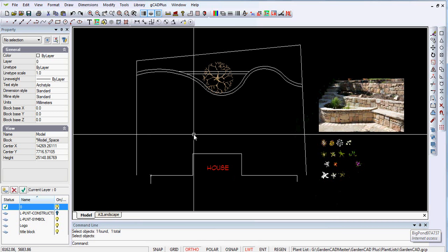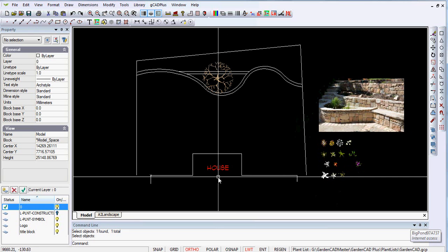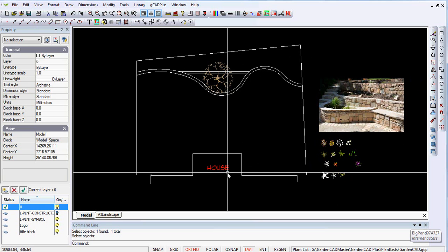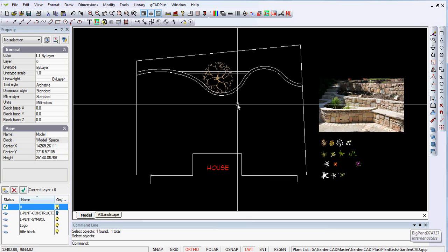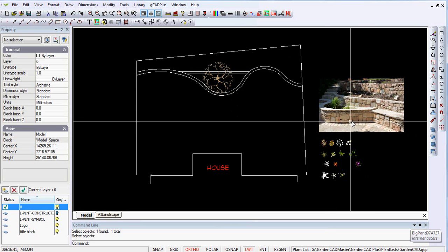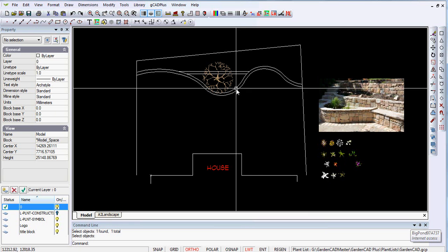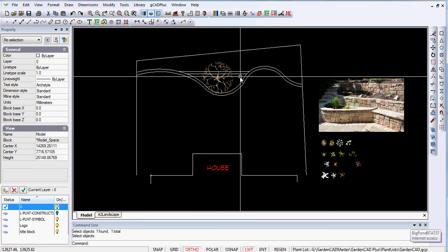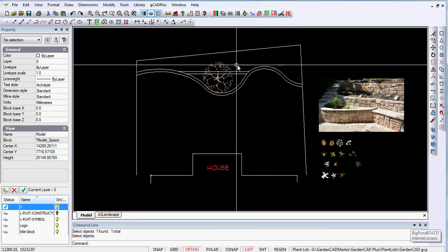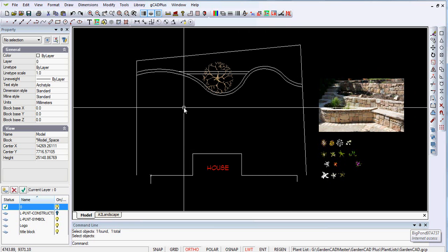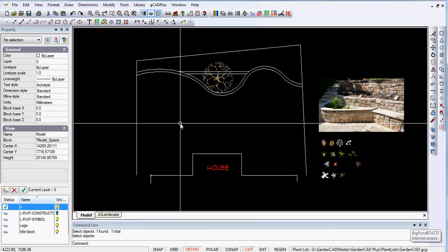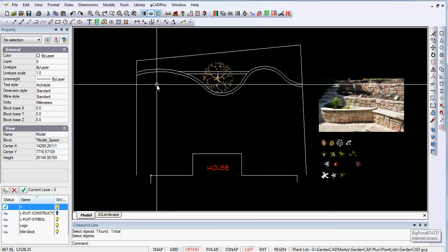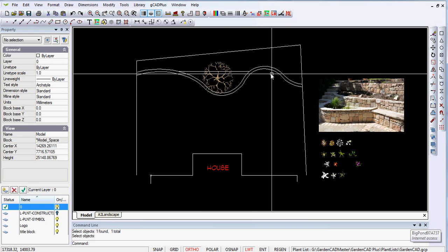So we're building in the hardscape elements, if you like. If we have a view from the house straight out here with that tree as a focal point, provided the height of the capping on the wall, and I haven't drawn the capping in yet, is at seating height, you'll have a nice effect such as we see here. And we can do some planting in and around that tree, and we could then have another retaining wall back through this area. But I'd leave you to put that in much the same way as we put in the first of those. Remember, we have retained these as arcs, so we could find the centre of each arc to create that particular pattern.